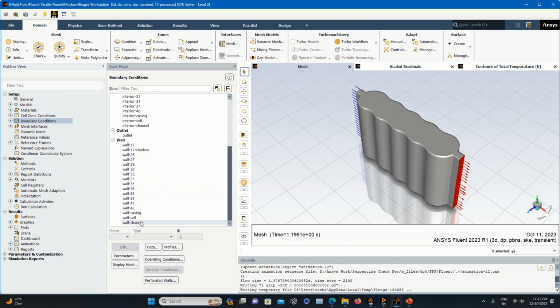Okay, now this is one simple geometry where we have used only 5 cells, but if we consider the actual model, which involves a lithium battery pack with around 70, 80 cells, it will be quite a difficult task to enter values for each and every one of the 70 cells. So that is one thing you need to always remember when applying the boundary conditions. The preparation has to be done right from the geometry itself, so that there will not be any difficulties in the later parts.